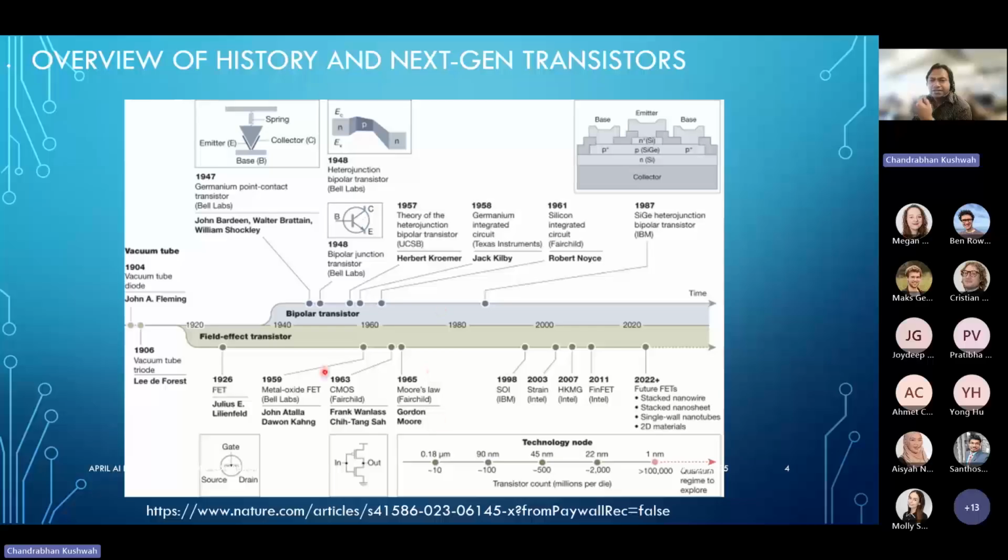And the inherent characteristic of CMOS circuits, notably the use of both PMOS and NMOS MOSFETs and their field effect operation, allows for extremely low leakage, because when PMOS is on, the NMOS is off, and when NMOS is on, then PMOS is off, and there is no such high leakage current, very tiny leakage current. So this was the very crucial circuit design, basic template for the big architectures. So this made an ideal situation for energy sensitive applications.